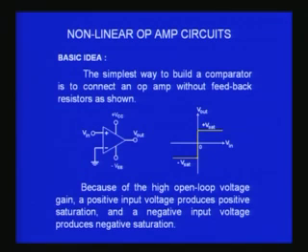So you can therefore detect voltages which are larger than some minimum by looking at the output of the operational amplifier. When the output is plus VCC, you know the input is larger than 0 volts, which is the other input of the operational amplifier, and when the output is minus VCC, you know the input voltage has gone below 0 in the negative direction, and that is why you are getting minus VCC. That is also seen from the figure that is shown by the side of the circuit.